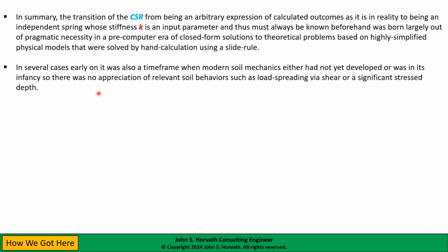In several cases early on, it was also a time frame, again, in the 19th century, early 20th century, when modern soil mechanics either had not yet developed or was in its infancy. So I think there was no appreciation of relevant soil behavior such as load spreading via shear or a significant stress depth. Really, one can't fault these early researchers about not knowing about something which simply was not known at the time.